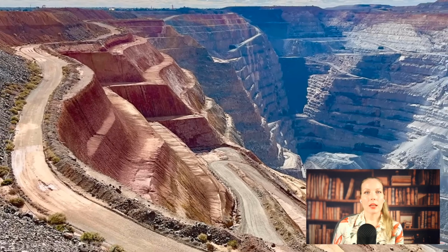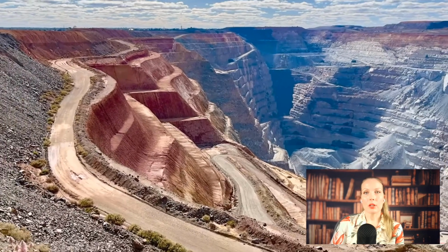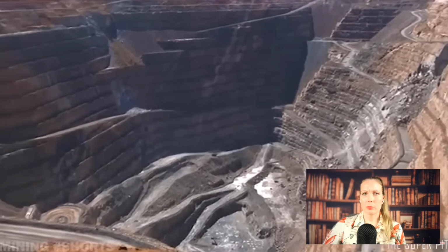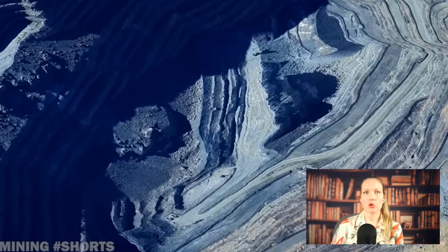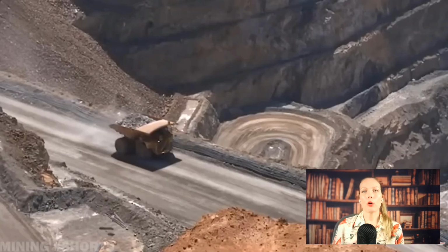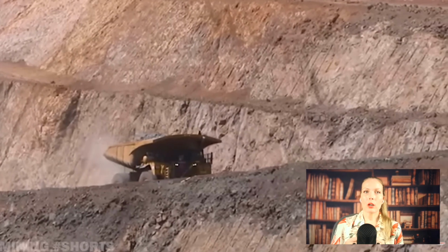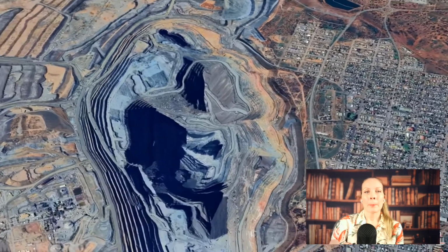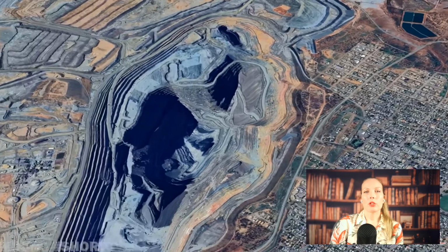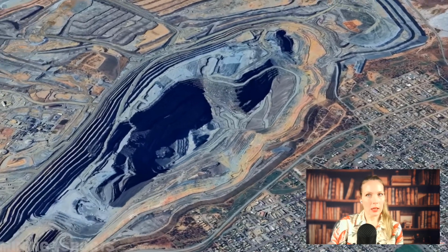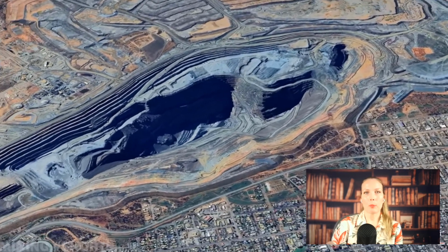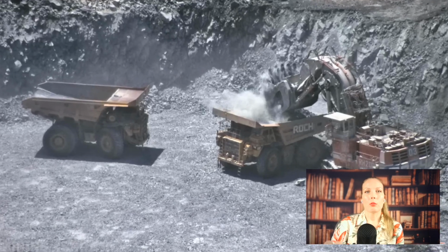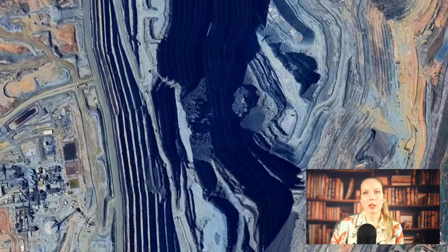Back in the 70s at the Morenci copper mine in Arizona, they started using pushbacks for smarter mine planning. It was one of the first big projects to put this method to work in managing a large open mine. They managed to lower the cost of moving materials around and reduce losses while developing the mine. By planning each pushback with geological details in mind, they not only cut operating costs but also ramped up productivity. Plus, because everything was so well coordinated, there was less downtime for equipment since they could use it to its full potential.